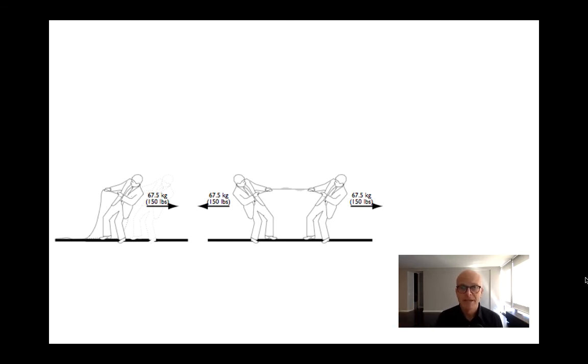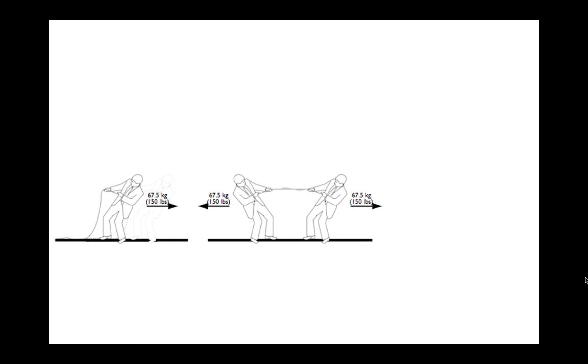It'll be balanced. Now, notice what's going on here. There are two external loads being put onto the rope, and the rope is developing a state of stress internally. And in this case, we call it tension. The rope is being pulled apart. So it's in equilibrium, but it's only in equilibrium because it's developed this internal stress that's able to balance the two forces, the two loads being applied on either side.